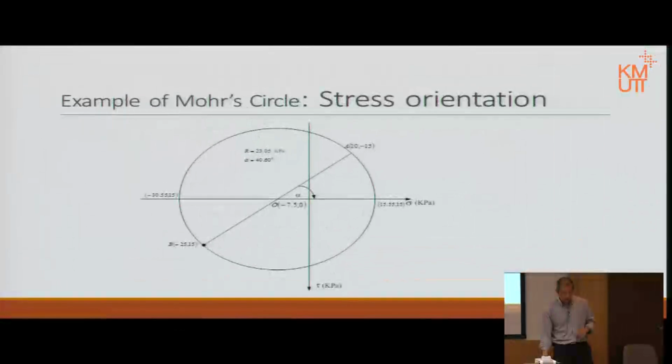Then let's look at the stress orientation. We start off with this picture. The question said they want to rotate the angle by 10 degrees clockwise. In this one, physical is theta, and on the stress plane in the calculation it is 2 theta. So if physically you turn 10, here you turn 20, and then we have these lines. From there, x becomes x prime, y becomes y prime. Let's call that point D.